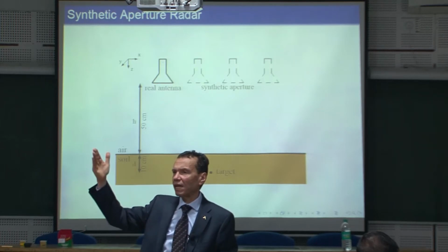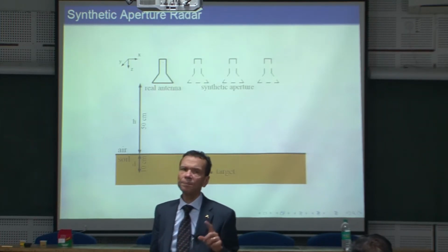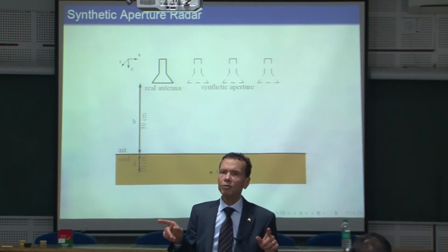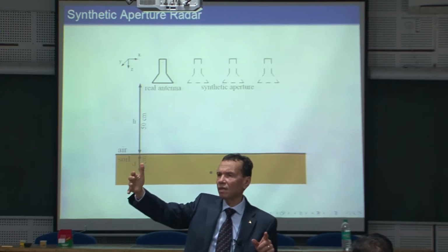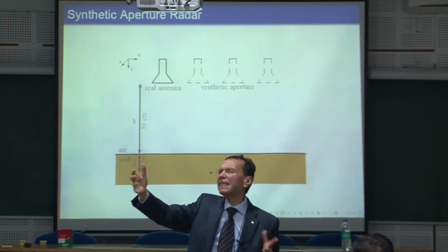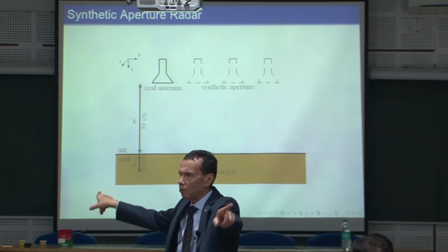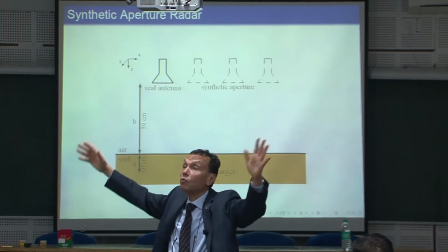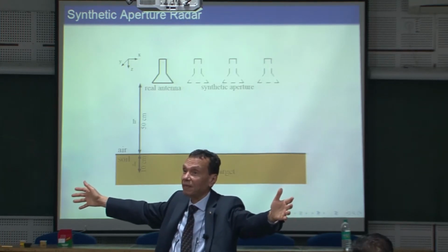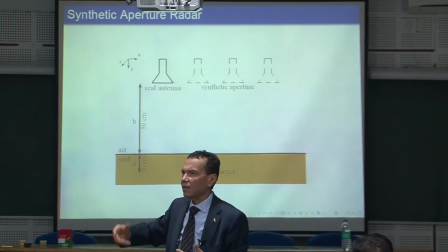Imagine that your reflector reflects 80%, because through the side lobes you lose energy in other spaces. Of course, if you have a huge metal plate, but this is not practical. So you include this calculation into your calibration.